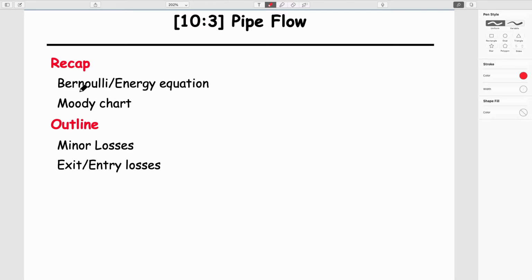We've made the point before that what we're using is the energy equation, which is the Bernoulli equation. If we write it again, and I'm sure you're maybe tired of this, it's defined in terms of the upstream components plus a pump head, equal to the downstream components, which would be these.